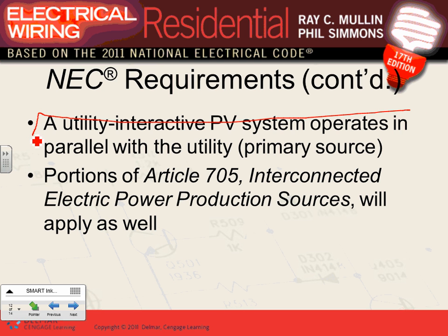This is really interesting for those of you who are going to work with interactive systems, which work in parallel with the grid. The interactive system cannot work without the grid. You have to have the grid. It senses no power, shuts down. It's not a backup system.